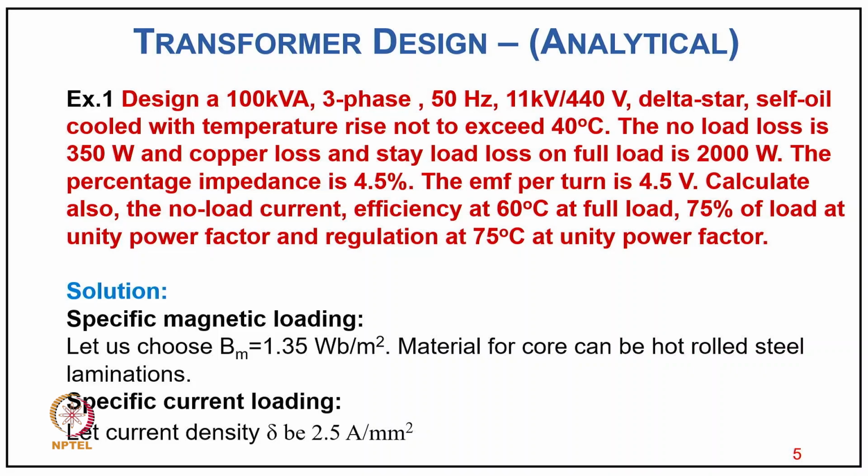The induced EMF per turn is 4.45 volt. Calculate also the no load current, the efficiency at 75 degrees centigrade at full load and unity power factor, and the regulation at 75 degrees at unity power factor.